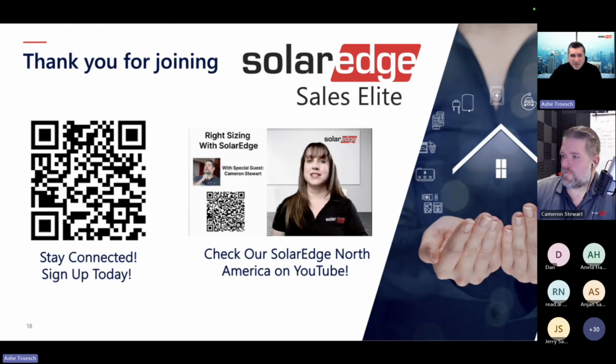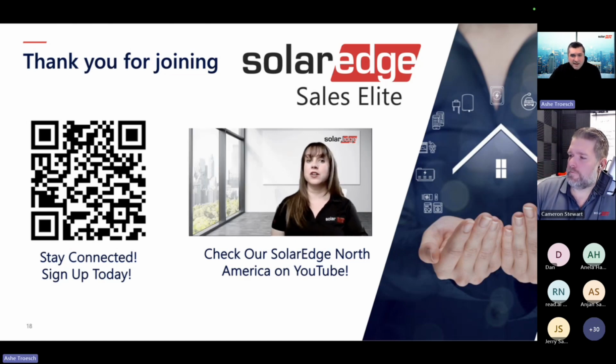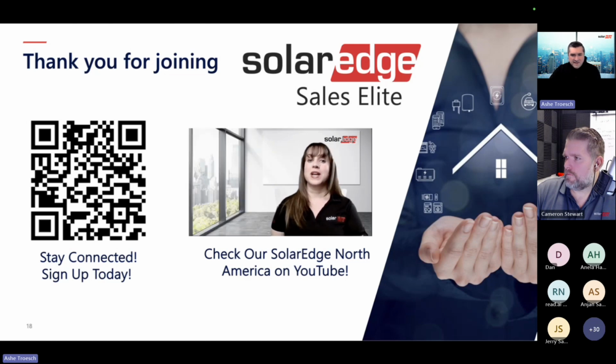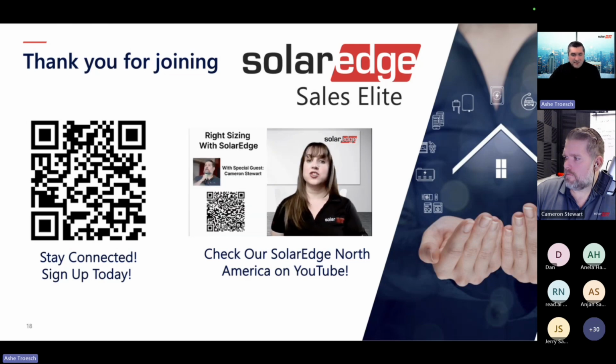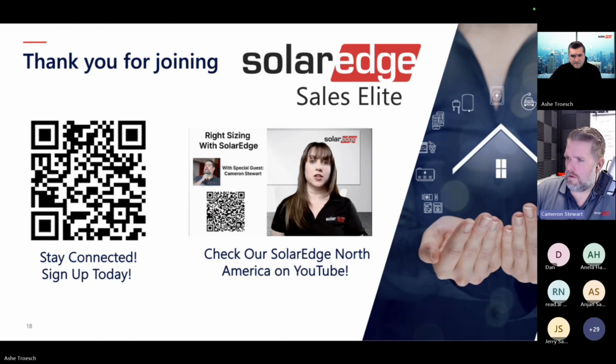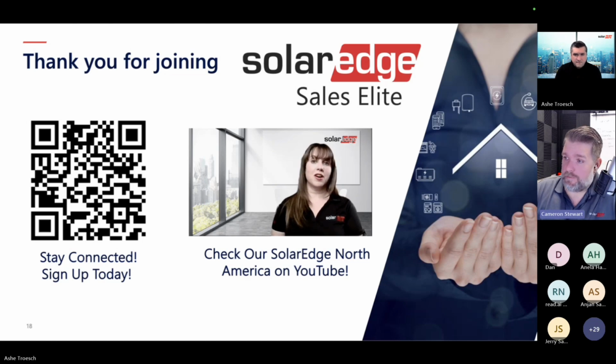All right, so the exact question, Cameron, was: as recommended, they always use the designer, but SolarEdge Designer doesn't seem to be allowing for the single optimizers on the U651 with the three-phase inverters. Is it a tech support issue, or does Designer need an upgrade? Yeah, I don't see why you would not be able to do single module on this optimizer. The spec sheet definitely says it. So I think you found a bug in the Designer.